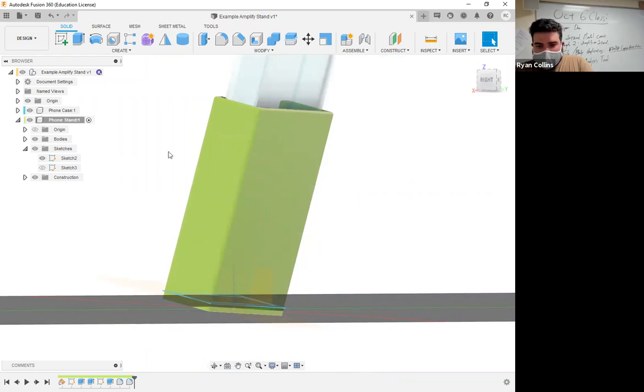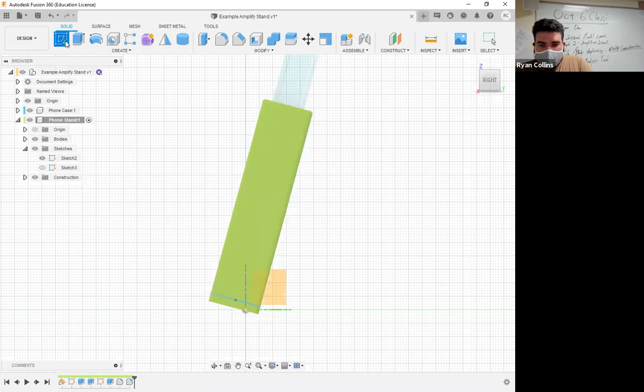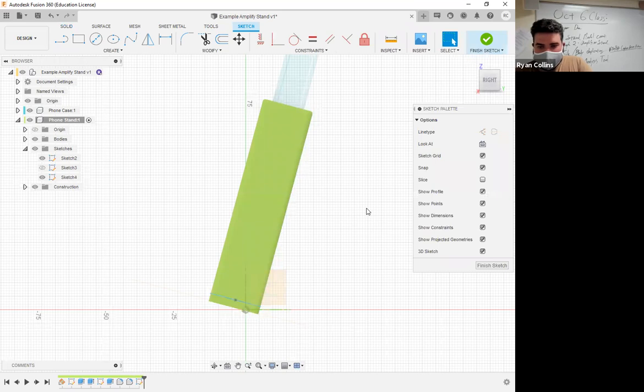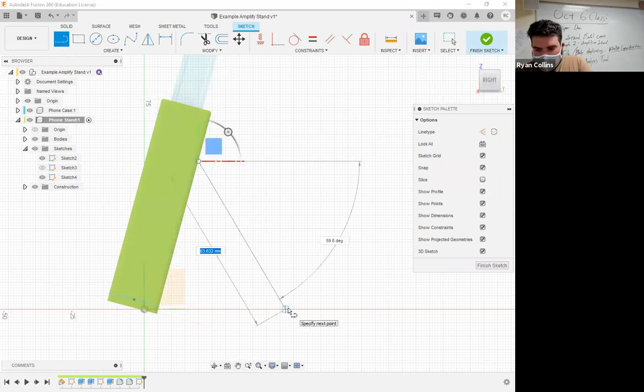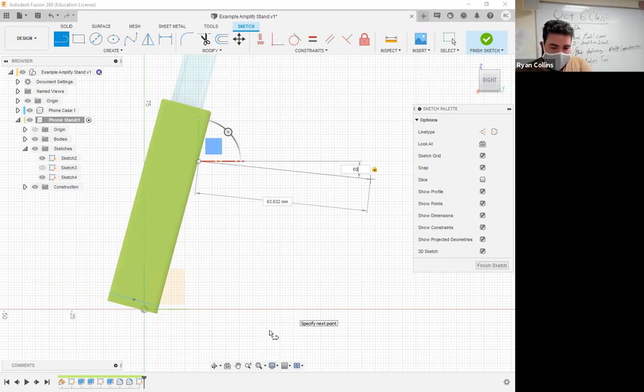All right, so now I do want to create a little kickstand here. So create a sketch, and on this part, I do want to use one of the origin planes simply because I'm working straight up and down. Now then, let's see here. Something at an angle. We'll say it's a 60-degree angle just because it's a round number. Goes down to the construction plane. However, you know what? I want it to line up with the bottom of that point.